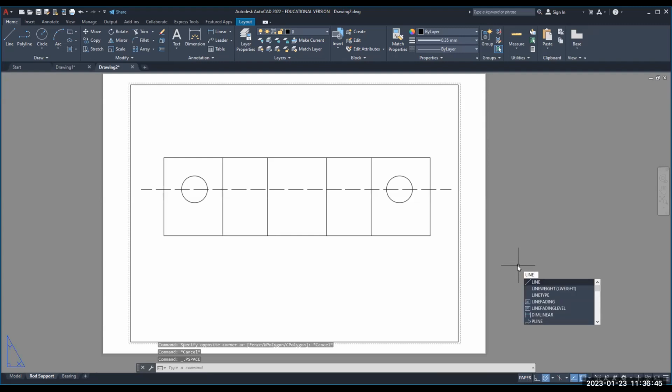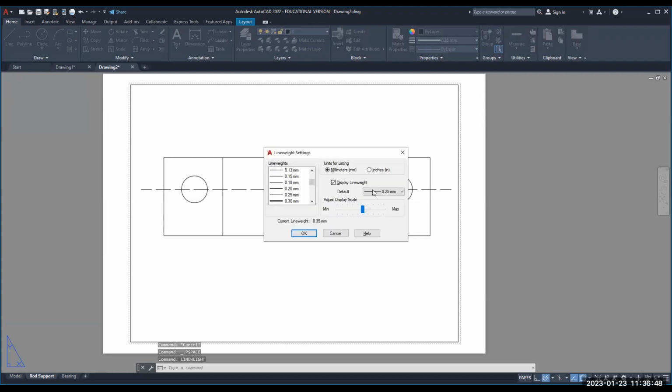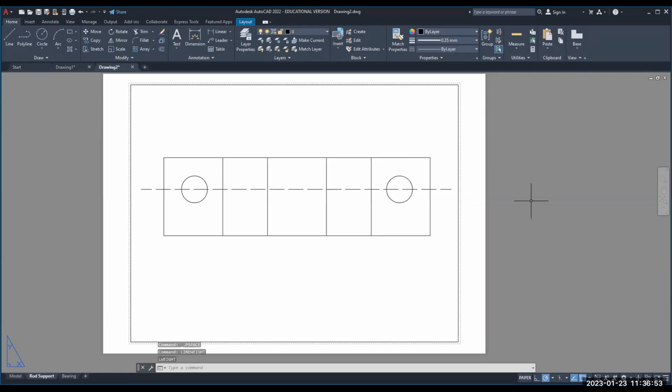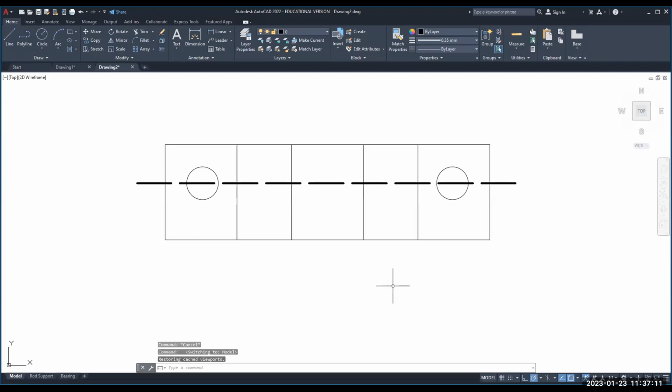Incorporate into a template? Yep, absolutely. Anything that we do. Or you can change your template as you go. Just add to it and resave. Like if I'm still drawing and I change a setting, I can save that as a template, but without including the drawing. But actually, for starters, it might not be a bad idea to just keep doing that. You can do that and then just erase the drawing out of there and resave.